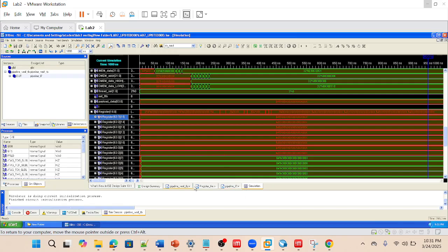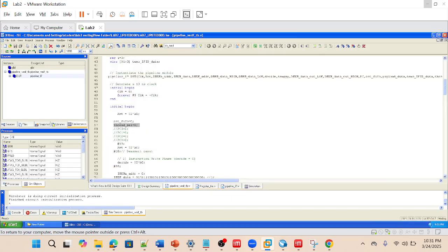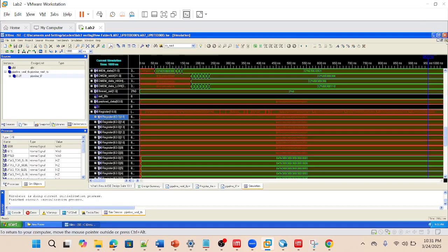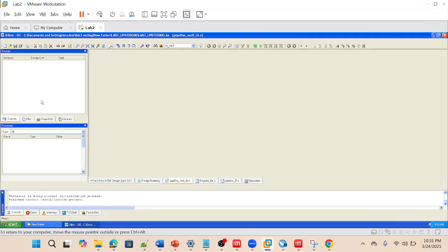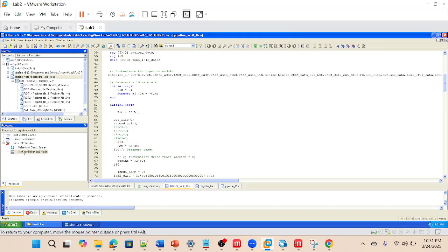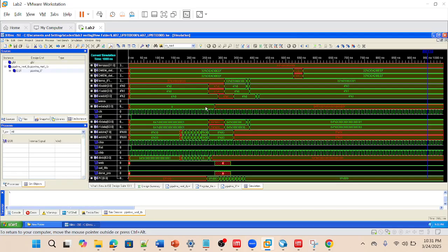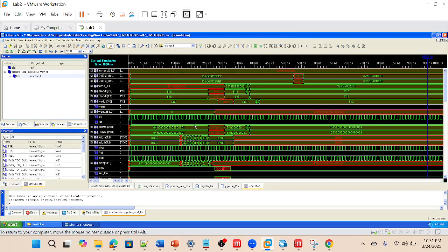In the same way, in the test bench environment, instead of thread select 0, if we give thread select 1, and rerun the simulation, you can observe that register file 1 will get updated instead of 0, 2 or 3. I'll rerun the simulation so that you can see the changes. We also tried various operations like load word and store word for each of the register files, and ran various kinds of commands as well.